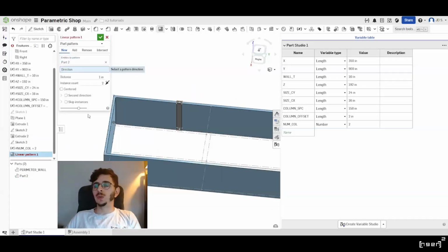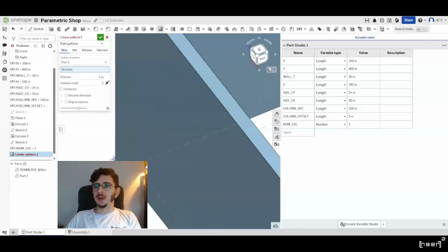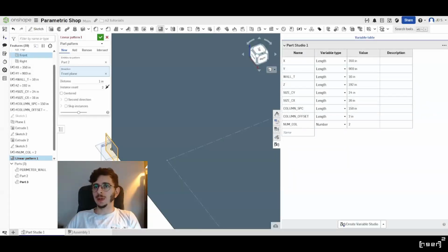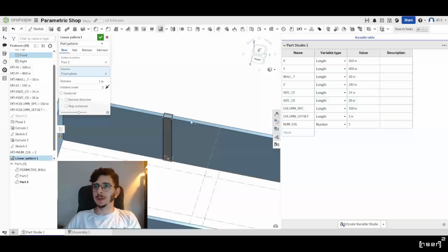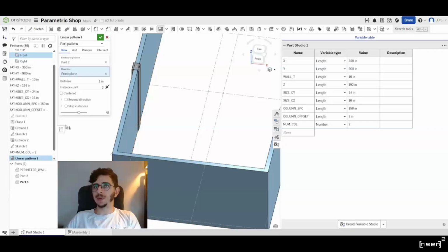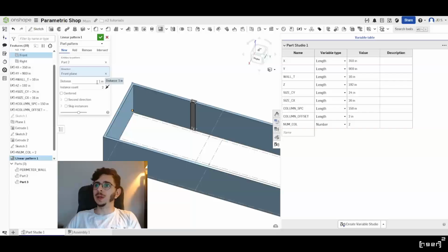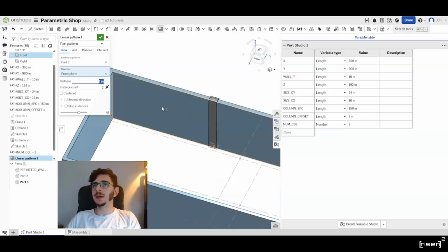For direction, we are going to use a solid reference line that will not change from the earliest part of the model. In this case, I like to use the planes because those will never go away. Alternatively, we could use the sketch one long line, but plane is a better reference in this case.